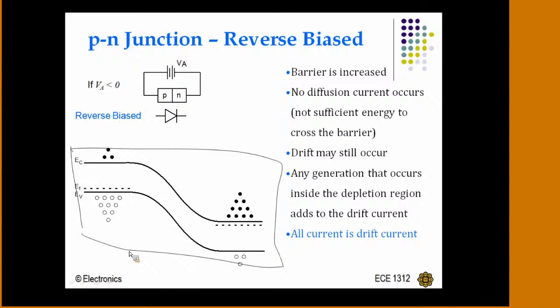Now see here, in the case of forward bias, the conduction band of the P-type and the conduction band of this N-type will be almost in parallel. But in the reverse bias, there is a height. In band diagrams, we call it a height.